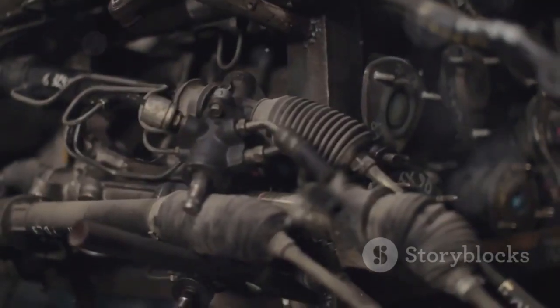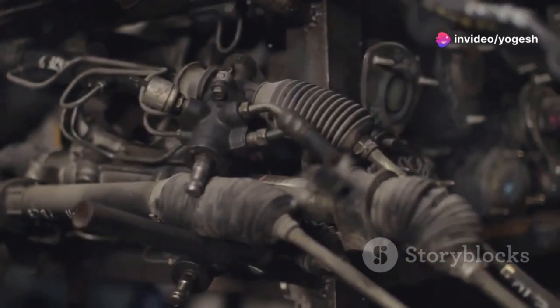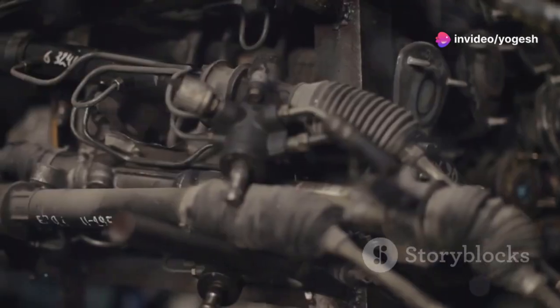The offset section is designed for parts with staggered or non-linear internal features that a straight cut would miss. Here, the cutting plane bends or jogs to pass through all the important features, allowing you to display multiple details in a single, comprehensive view.